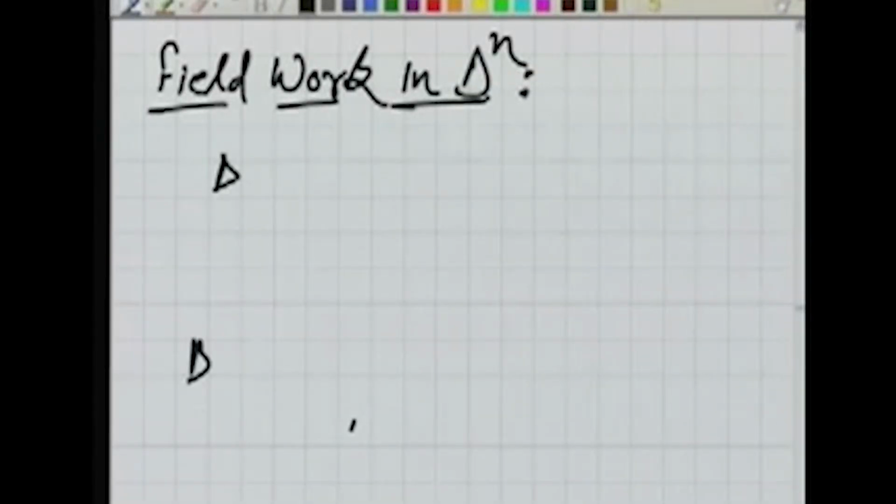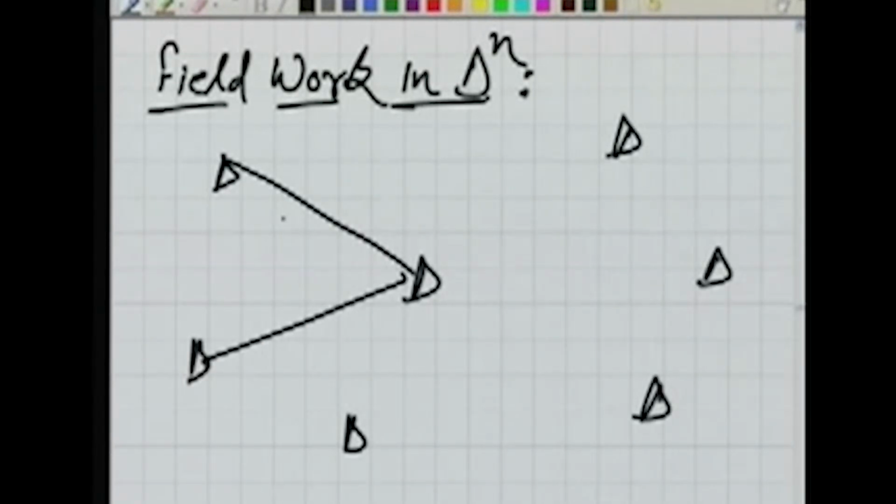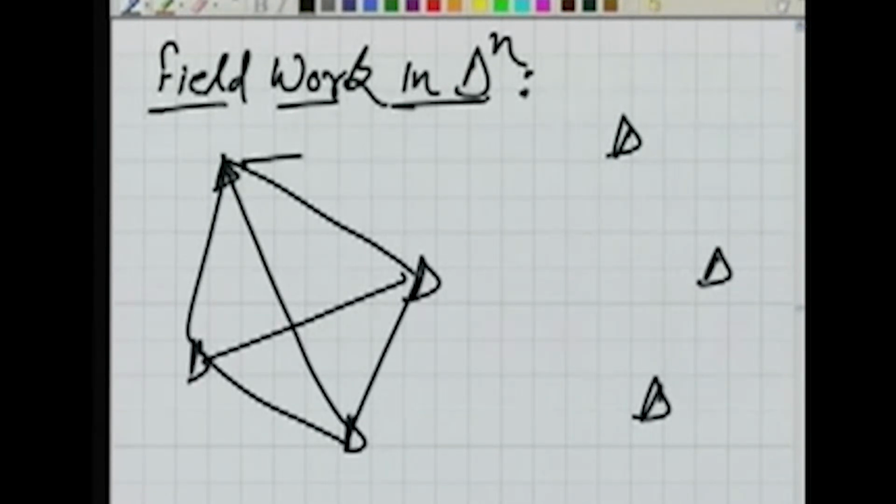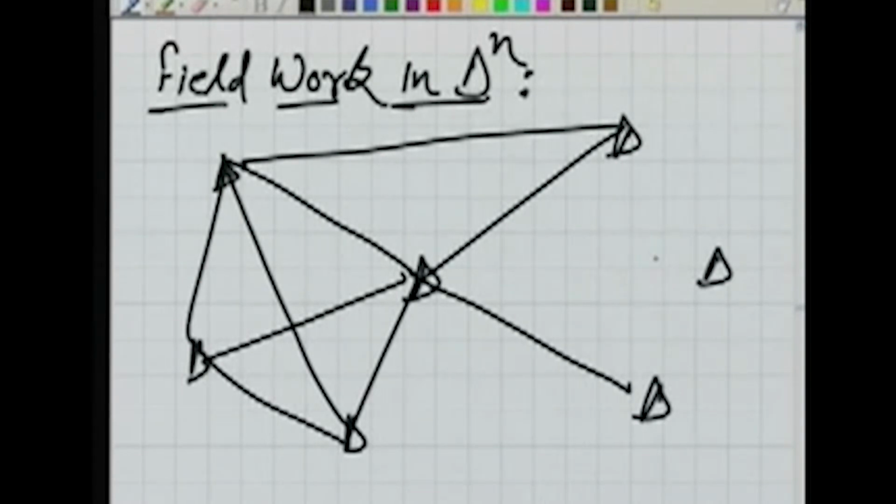So initially we are establishing some stations which will form our triangulation stations. The moment I establish these stations, as here in this figure, by visiting the field, I am deciding the form of my triangulation network, how it will look.